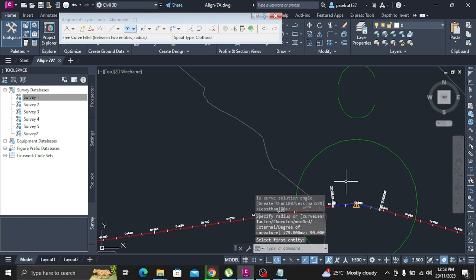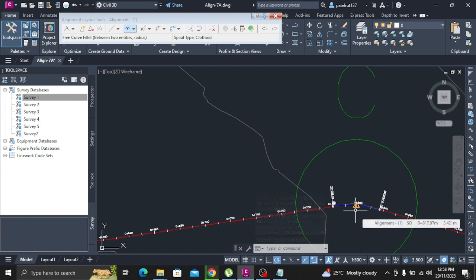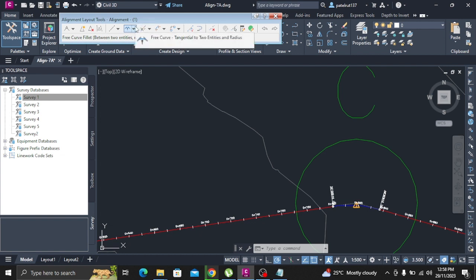Open align7c.dwg, which is located in the Tutorials Drawings folder. In the drawing, select the alignment. Click Alignment tab, Modify panel, Design Criteria Editor. On the left side of the dialog box, expand the Alignment's Minimum Radius Tables collection. The collection contains several minimum radius tables.